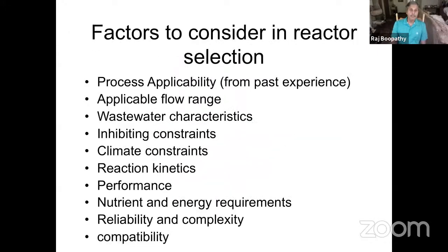Yes, here. So when you design a reactor, you need to know what process you're applying for. There is a lot of wastewater out there, right? Not only municipal wastewater, but different factories producing different chemicals, the food industry, the leather industry, and all kinds of industry. You need to look at what kind of waste you are dealing with. And again, you need to know the volume of waste generated. You need to do the analysis of the wastewater, and then look at whether there is any toxic chemical in there that can inhibit microorganisms. If that is the case, you need to design a pretreatment.